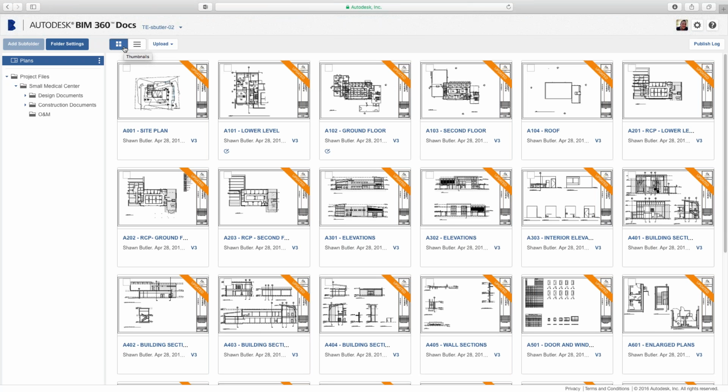So when we look at the functionality we're looking for, when documents get loaded up into BIM 360 Docs, we want them to be entirely present in the cloud. However, we are allowing for native file pathing that's going to allow you to, at some point, take that data and put it in locations where you want it for things like archival backups and information for a later time. The big thing that we're not allowing you to do in most instances is be a non-control user. So as an example, if you had just publish, view, and edit, and be able to extract that information down to your working machine. And there's a reason for that, right?